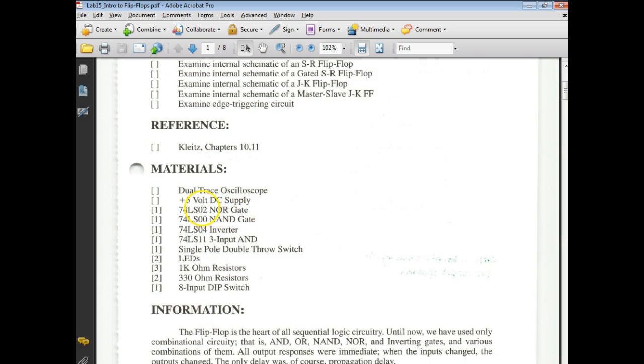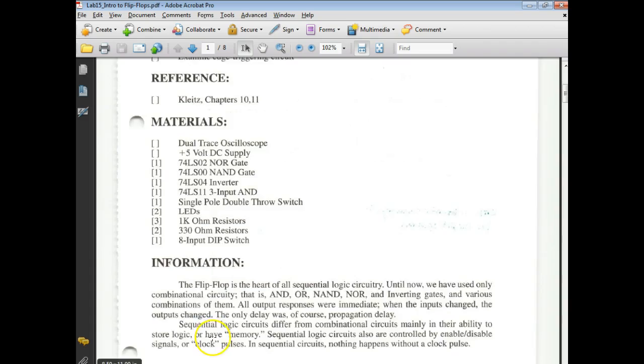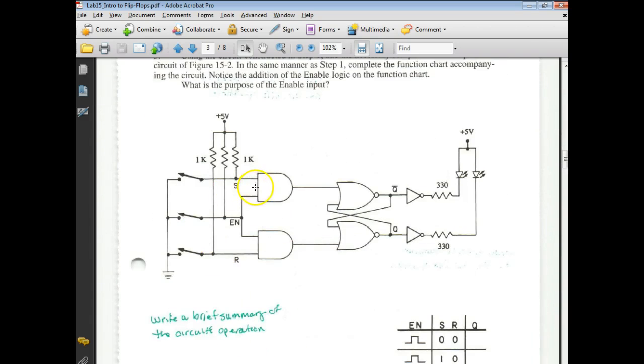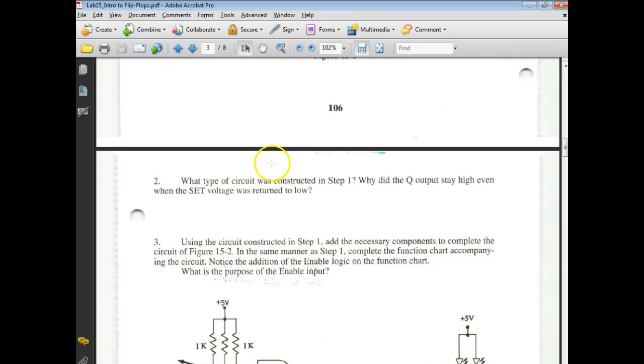These were the options it gave us on ICs. Now we could have done this, guys, but notice the AND gate they want us to use. What AND gate do they want us to use? 7411. Okay. But when we look at our schematic, it calls for a 2-input AND gate.